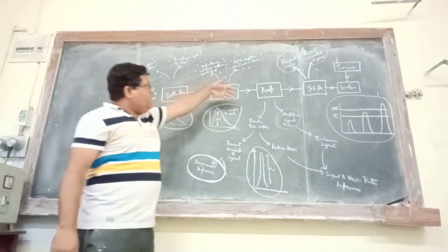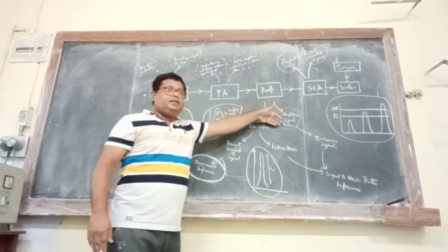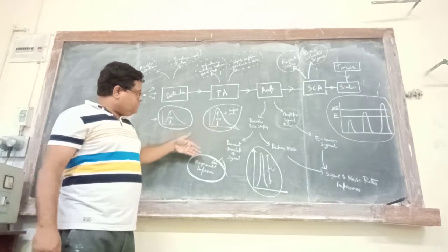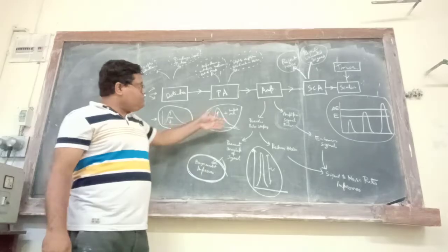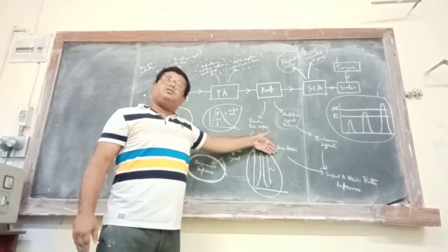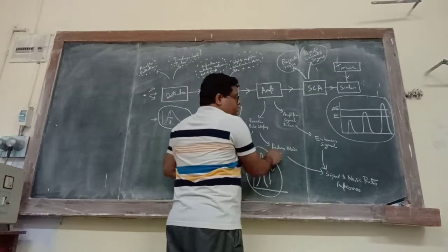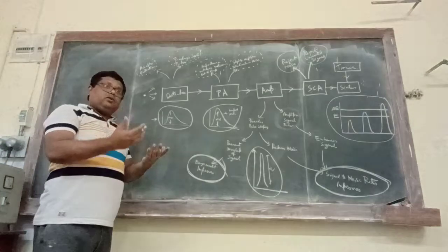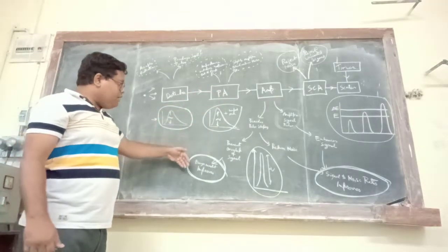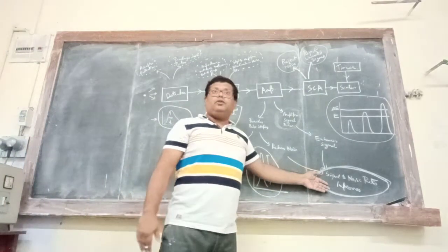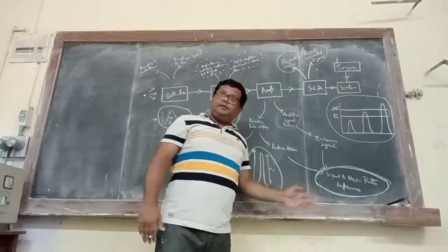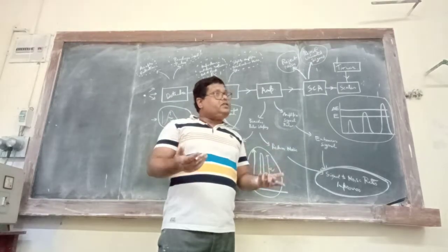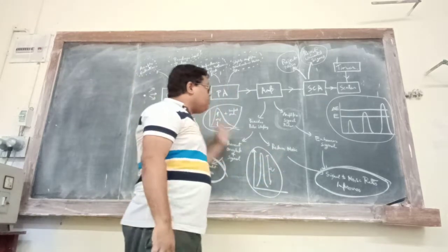Okay, let's continue. So the amplifier not only amplifies the signal, that means enhances the signal, but also provides pulse shaping, thereby preventing overlaps of pulses and improving the energy resolution. Now you see, this pulse shaping also reduces noise, and together enhancing signal and reducing noise causes the signal to noise ratio to improve. This is very important. So using a very good amplifier, not only are we able to improve energy resolution, in fact we are able to improve the signal to noise ratio as well. Keep this in mind. So just having a good detector is not good enough. Remember, I talked about the properties of energy resolution, efficiency, peak to total ratio, but that was only for the detector. And now I am talking about the entire system.